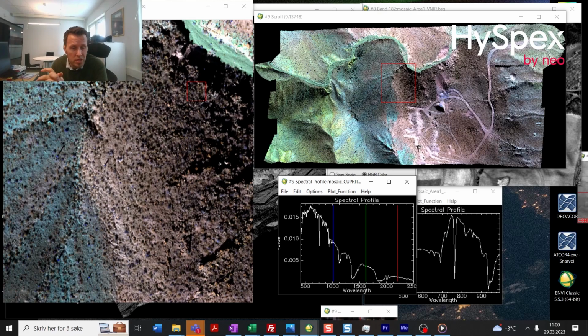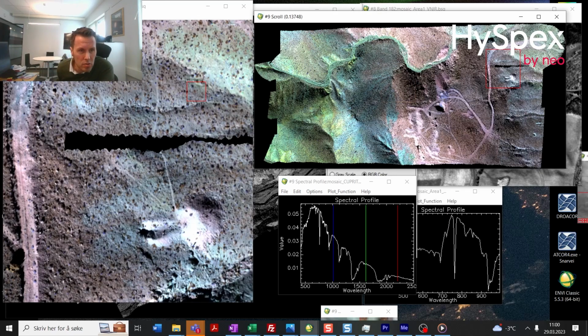Some suppliers don't even supply a sensor model with their cameras, which means you will never be able to get a good georeferencing. You need a high accuracy surface model. You need your cameras bore sighted. You need your LiDAR bore sighted. When you have full control over all these things, then you have the possibility to make some good data products,